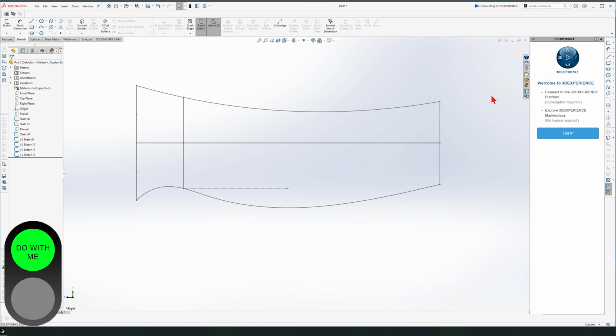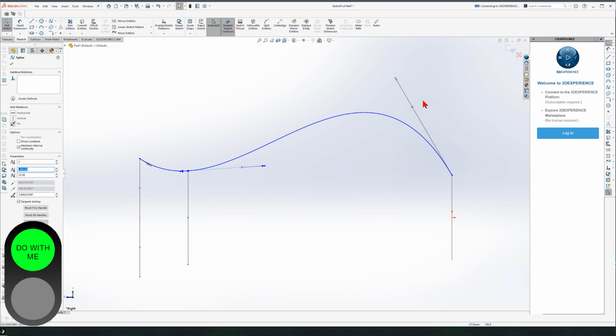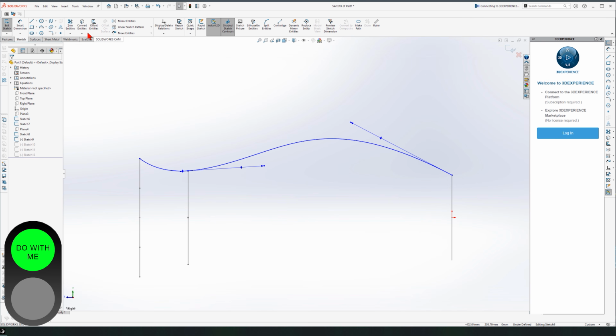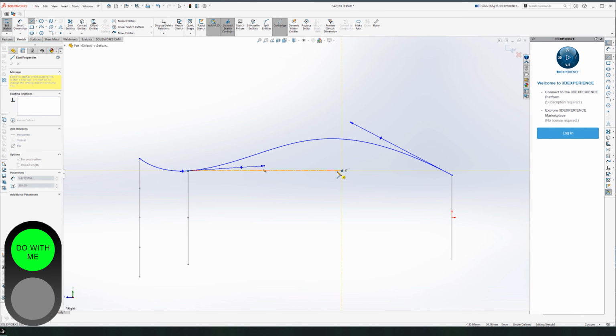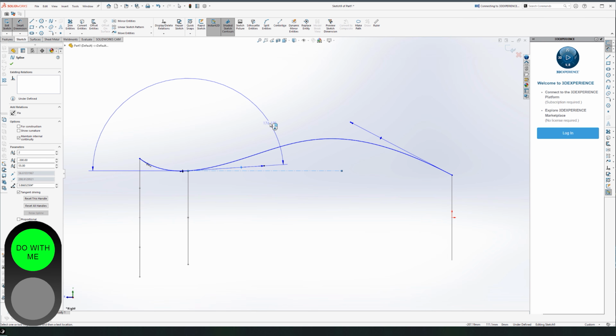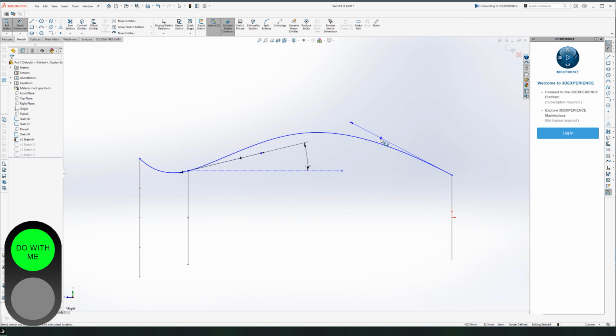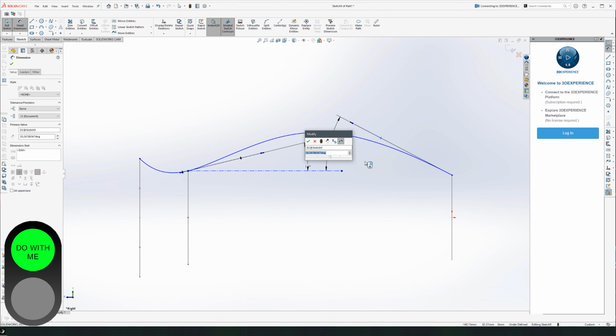Now I'm going to rebuild this. We would like to change this one too, right? This is concave. So edit, click on that. Edit, click, drag from the diamond, drag from the diamond, okay? Center line from here, horizontally to the right, press escape. Then we press smart dimension, pick the center line, pick the diamond, and make sure we are not clicking here. We're clicking inside, so we can type 14. Again, diamond to the center line, 14.